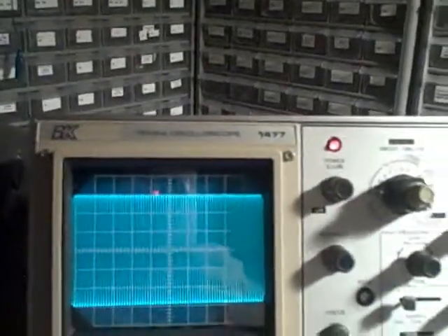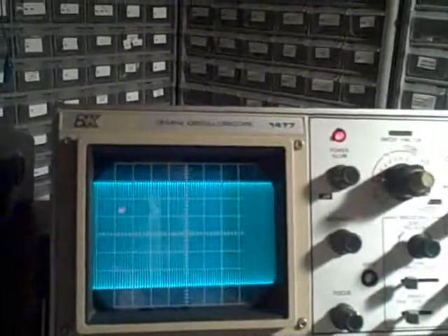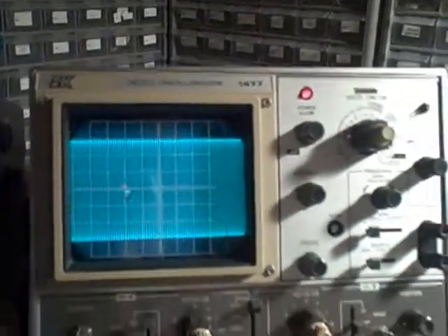So we actually have a little bit more frequency response available here than the rated, which is good. So you've got just a little cushion there. The scope seems to be functioning well and is very comparable to our reference scope over its frequency range.